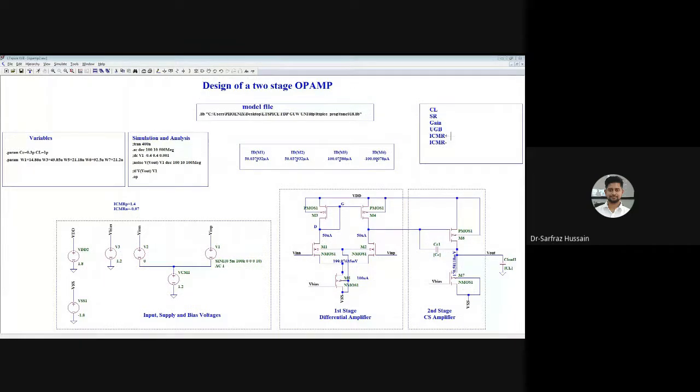The positive common mode range actually gives us the maximum input that we will apply as a common mode, and negative is the minimum voltage that we will apply. Now in this design, there are two more specifications that we want, VDD and VSS, so that we can choose what we want. It can be based upon our model files or our requirements. So we can choose what will be our VDD and VSS, and based on that we should look into this. ICMR positive and ICMR negative will actually tell us what our VDD should be.